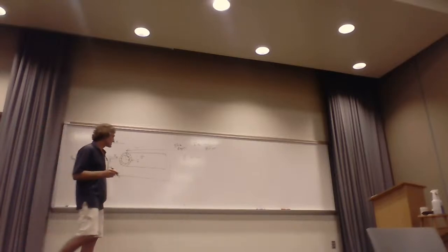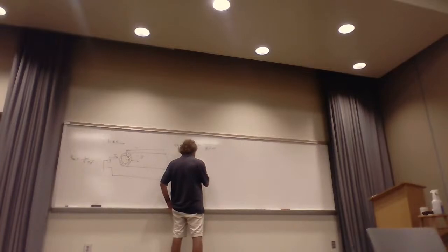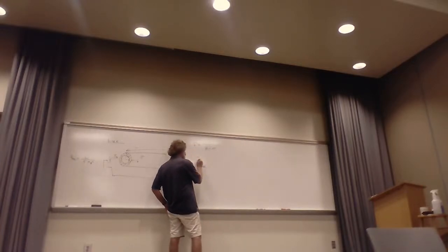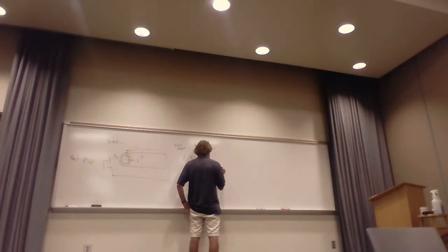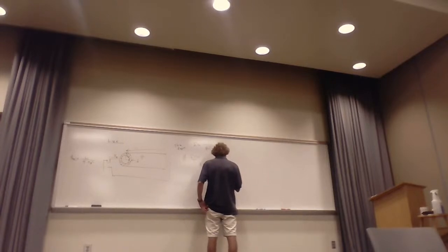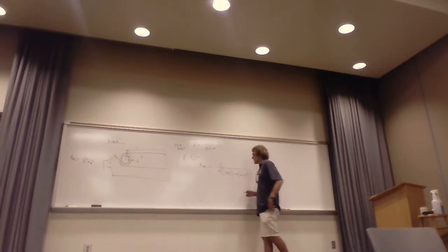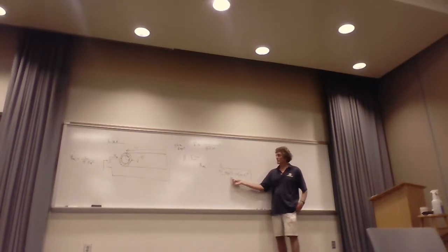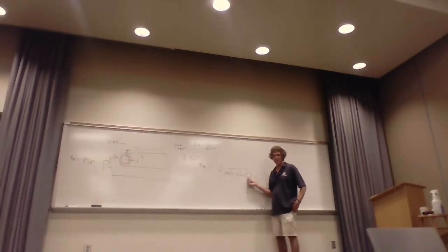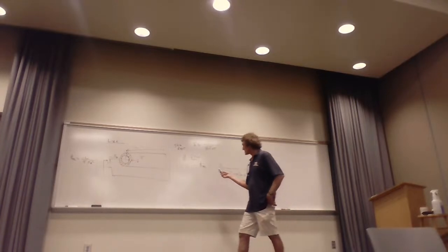Now, the general way to do this is to say that the resistance, this is RAC, when this is true, is equal to simply the length over sigma, and then it becomes pi a squared minus pi, and then it's a minus the skin depth squared. If you look at this, that's the area that would be associated with the current equally spread over the cross section. But you have to subtract this inner core area off. That's why you have that. Y'all remember that, right? Now that's RAC if this is true.